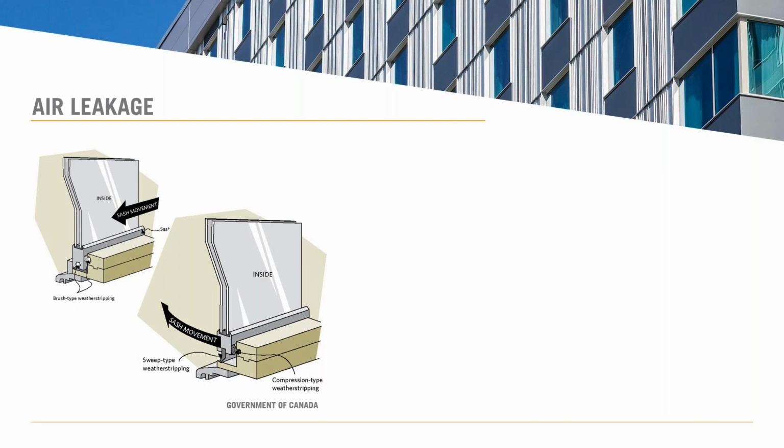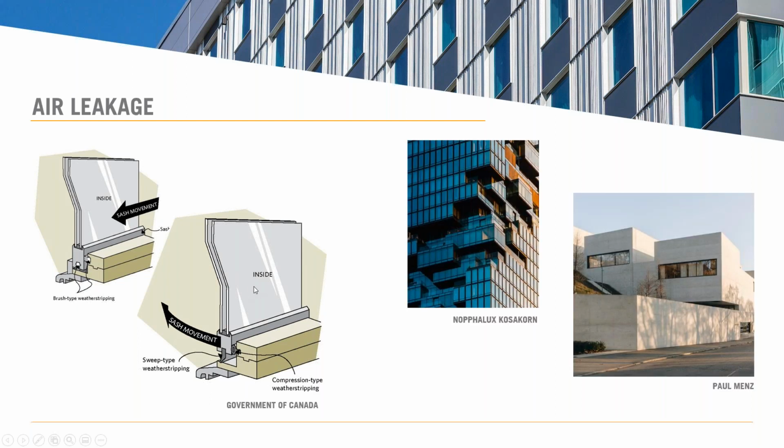If you imagine the hatch on a boat, the best seal is going to be in compression, like I already mentioned in the window design area. So why does it matter? Like I mentioned, building energy performance standards require air tightness as a measure of whether you've achieved your proper envelope design. So the building is pressurized and they measure the air changes per hour. And the windows, often a huge part of the envelope, contribute significantly to whether you're successful.